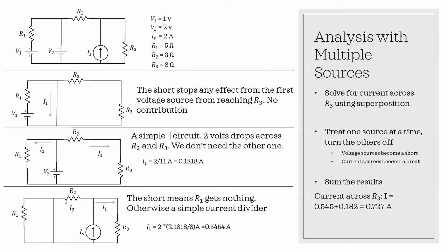And we're going to want the current through resistor 3. The general method or algorithm involves taking advantage of superposition and solving for each source separately and then adding. And remember, we can use superposition because circuits are linear. So the total result is the sum of all of the individual small bits. And right now we have 3 bits contributing to what's going to happen across resistor 3.